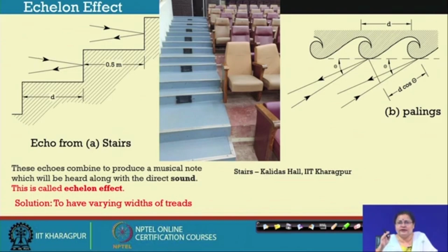So, no continuous repetitive form is encouraged within the auditorium, and again of particular dimension which corresponds to the wavelength which is being performed in that particular space. So, if it is less than lambda or 1/4 lambda, for 500 hertz it is 2 feet, for 1000 hertz it is 1 foot, for 2000 hertz it is half a foot.